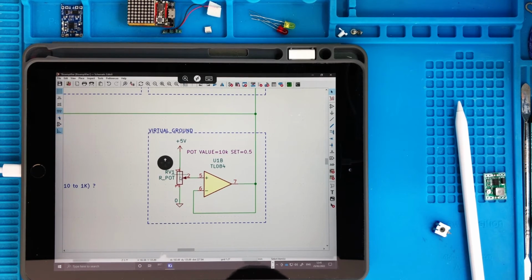So this resistor will become something like 2 resistors in series, and you take the middle point of them, and once those 2 resistors are equal, then this thing is getting exactly half of this voltage here, and this comes from the solution of this voltage divider. We can do this later as a simple calculation.